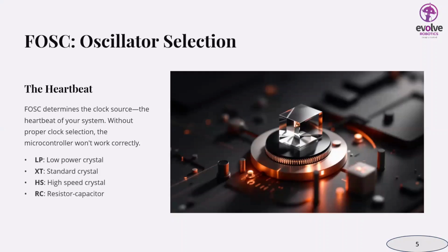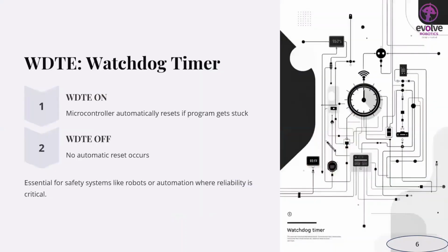The next bit is WDTE. WDTE stands for watchdog timer. If it is on, the microcontroller will automatically reset if the program gets stuck. If it is off, no automatic reset happens. This is very useful in safety systems like robots or automation.